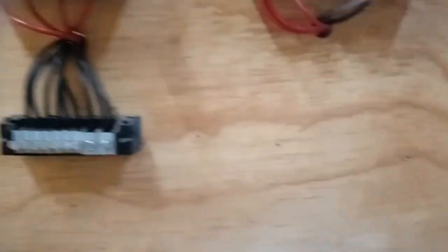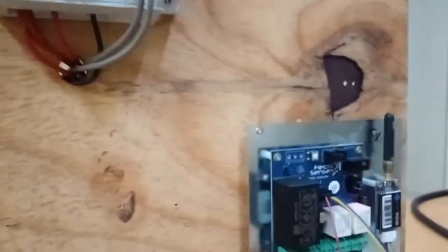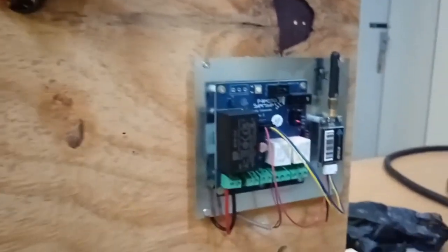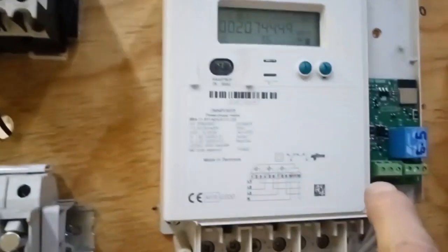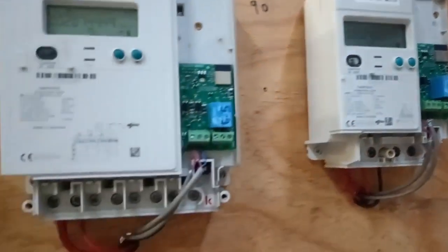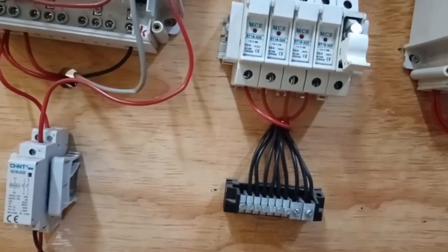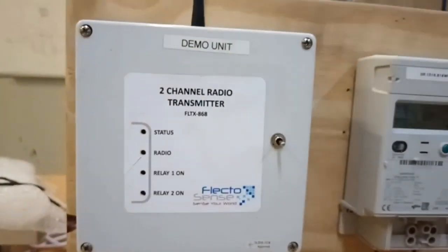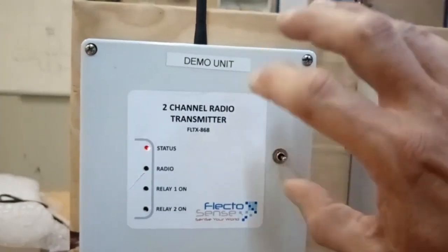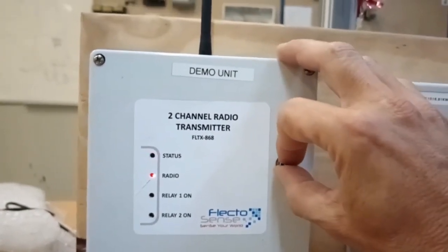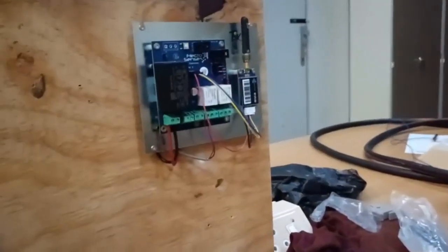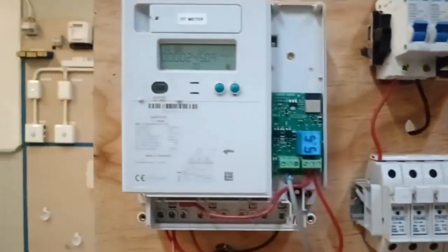And then the generator part of it, we have a radio. As I said, in your small building you can use a relay with a normal switch that you daisy chain to your input of this module. And I've just simulated one where the generator is very far from this meter room. So we have a long-range radio system. I'm simulating the generator switch here. That's the relay on the generator. So if the relay switches on, it will switch this receiver over here, and that will do the daisy chaining, switching all these meters to tier 2.